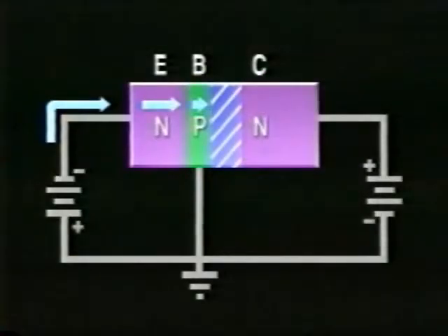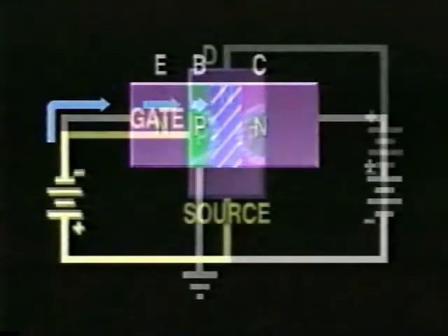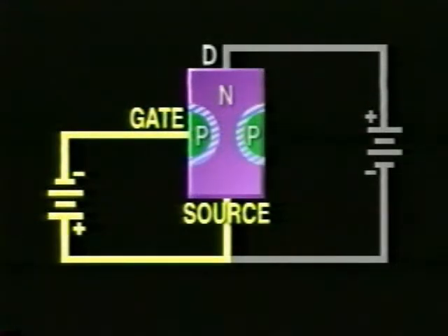Here is the JFET in a simple circuit. There is the normal diffusion of charges across each PN junction, resulting in the formation of two depletion regions. The way that the JFET is biased is very different from that of the bipolar transistor. While the emitter-base junction of the bipolar transistor was forward biased, the gate source junction of the JFET must be reverse biased, as shown here.